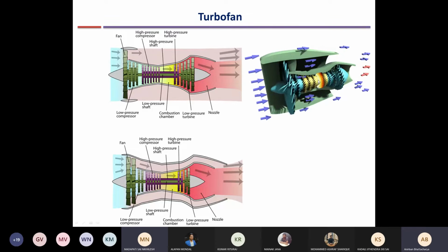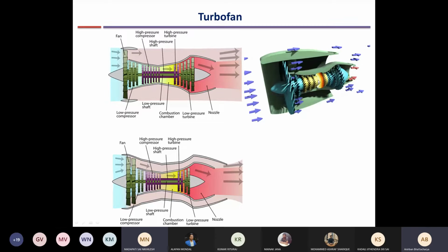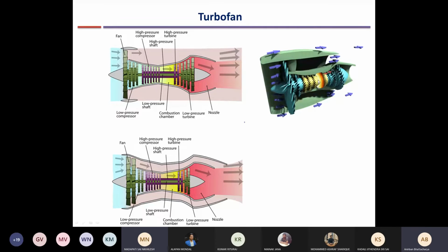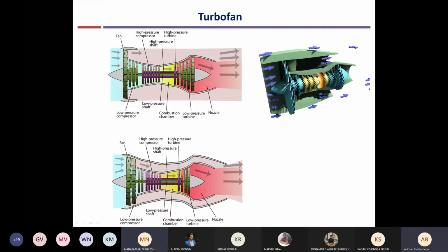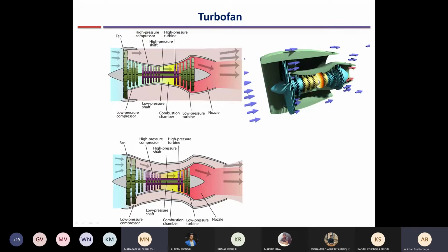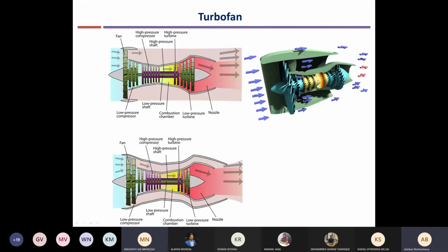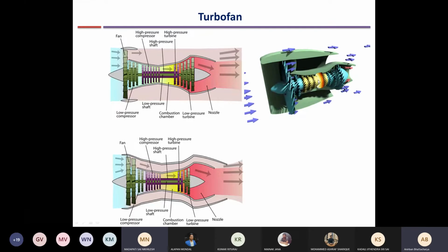Yes. So the increase in pressure occurs in the compressors stage by stage. So at the final stage, we reach the maximum pressure of the cycle. So in the combustion chamber, ideally the pressure remains the same. In reality, the pressure is slightly reduced because of turbulence and friction. A small, say 3 to 4% reduction in pressure occurs throughout the combustion, like flow through a pipe, you can say. But the pressure ideally remains the same. Okay.